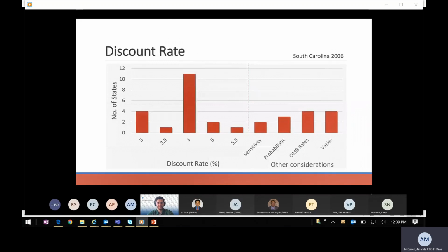So this is the portion where we're really getting into things that could be considered in step 0 of an LCCA framework. Now, the FHWA Lifecycle Cost Analysis Primer recommends the use of constant dollars and real discount rates. Real discount rates reflect the true value of money over time with no inflation premium. Now, when estimating future costs of transportation projects, discount rates play an important role.